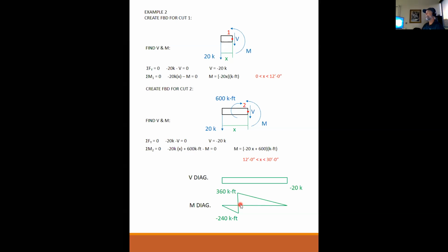So a steel beam is equally strong in negative bending or positive bending. If the bottom flange is in tension or the top flange is in tension, it doesn't make any difference. It's the same strength.